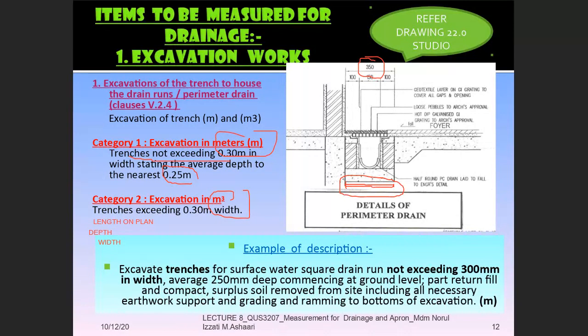Look at the last sentence, the second last and the last sentence. Details of the size and pipe must be given. If you look at the fourth layer, filling in, compaction and disposal shall be given in the description. That is actually to explain the last sentence. Whether you have to measure disposal and compaction separately or not depends on the information given.